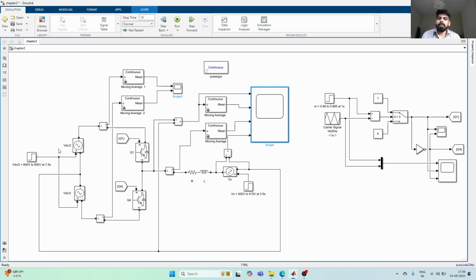We are getting some power from these DC voltage sources, and we want to control the power that is being delivered to the grid side. So how can we control that power effectively, efficiently? One of the things that we saw is that we can change the modulation signal to change that power. Basically, we were changing the current, the amount of power that was being delivered to the source side, right?